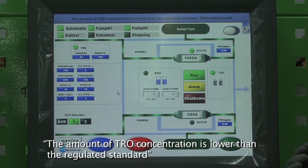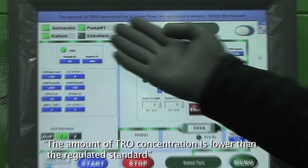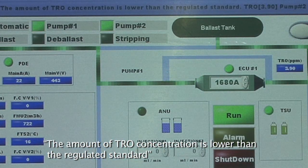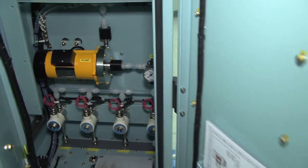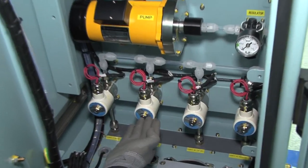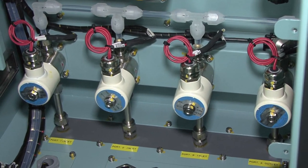Problem. ECS shuts down 10 minutes after alarm message. The message "TRO concentration is lower than the regulated standard" appears. Solution. Open the door of TSU and check that sampling water has flowed into TRO sensor.